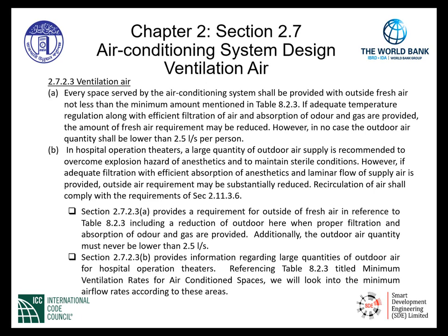In hospital operation theaters, item B, a large quantity of outdoor air is supplied and recommended to overcome explosion hazard of anesthetics and to maintain sterile conditions.